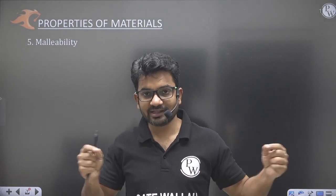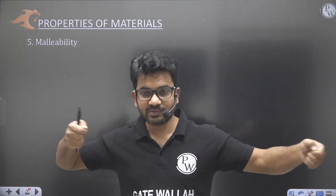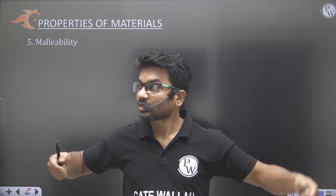So if I apply tension load and the material undergoes large plastic strain, then that material will be called ductile material. And if I apply compressive load and the material is able to undergo large plastic strain, then that material will be called malleable material. So ductile material: large elongation, large plastic strain in tension; malleable: large plastic strain in compression.